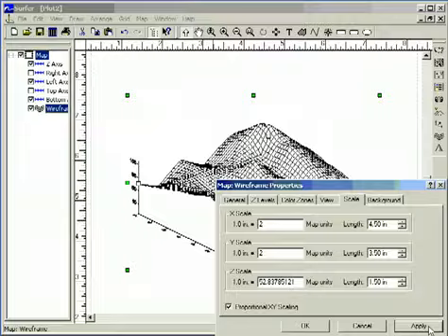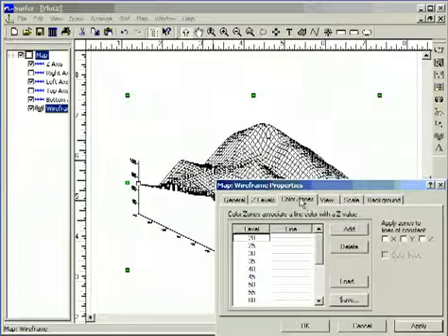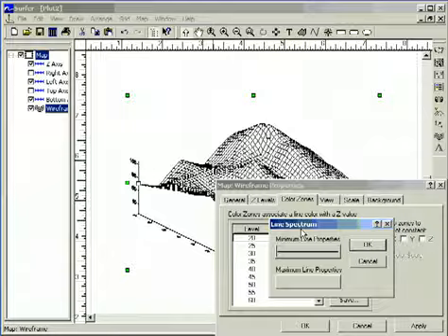To add color zones, select the Color Zones tab. To open the Line Spectrum Properties dialog box, select the Line heading. To select the colors you wish to use, click on the example color under the minimum and maximum line properties. I will first change the minimum line color.